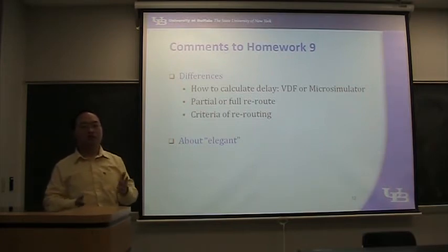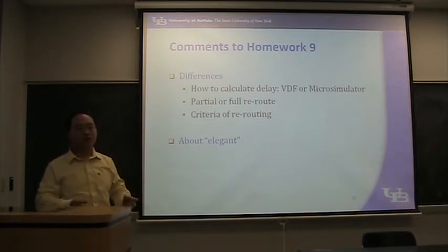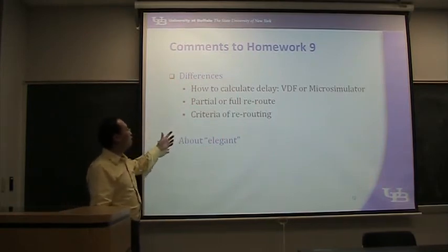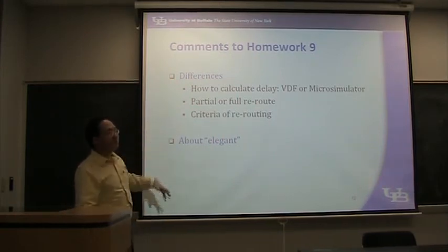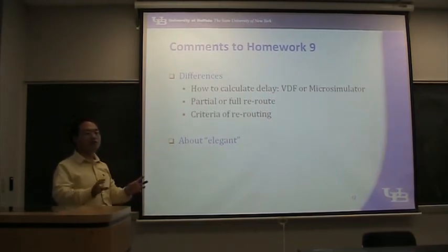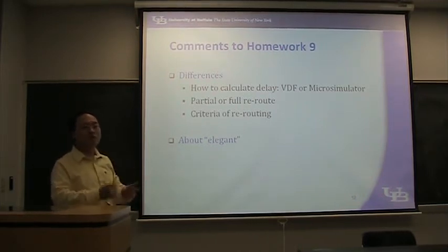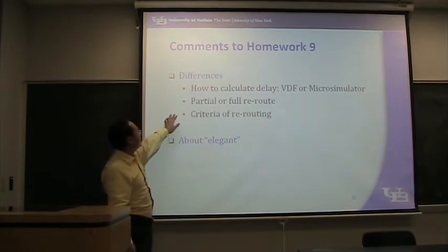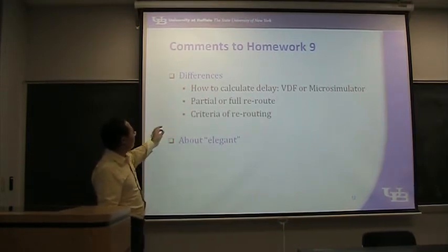Is it partial or full? It's still partial because you only change the way you calculate the travel delay, link delay. But for the third one, the user equilibrium, is it partial or full? It's a full reroute. Every time you reroute all the households, unless there is no difference. So the first 2 are partial reroute.